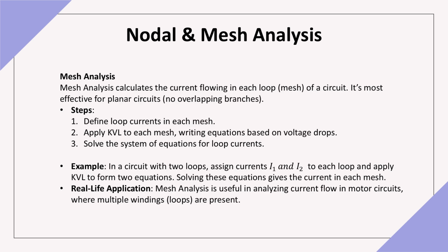Mesh analysis focuses on calculating currents in closed loops or meshes within a circuit. The method works best with planar circuits, those without crossing wires. Following 3 steps. Define loop currents in each mesh. Apply KVL to each mesh. Solve the resulting equations. This approach is especially useful in motor circuit analysis, where multiple current loops interact.